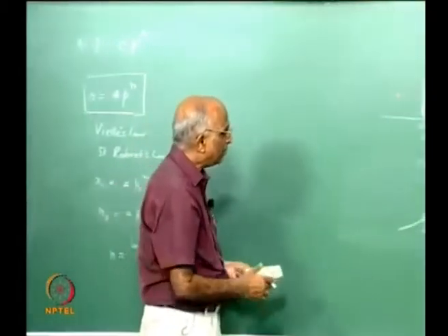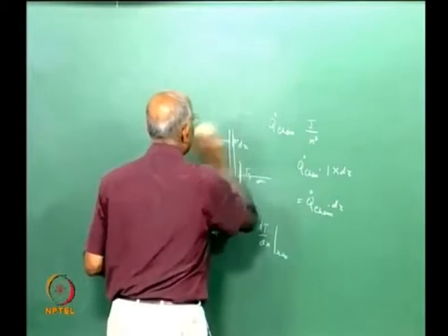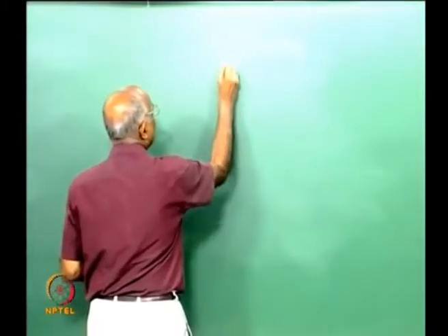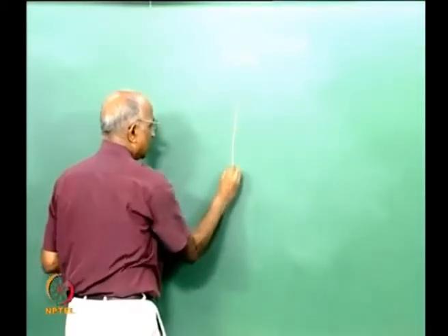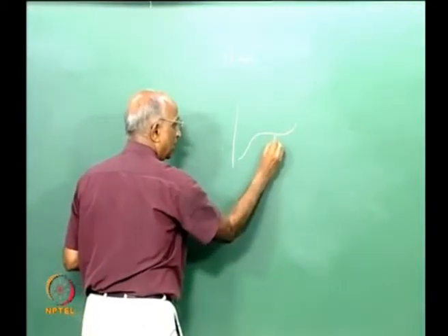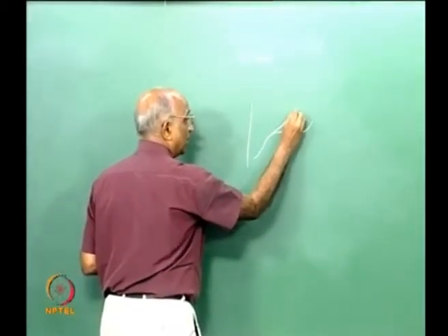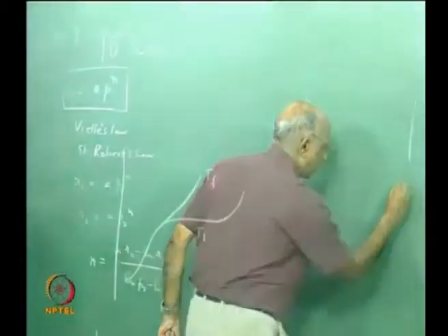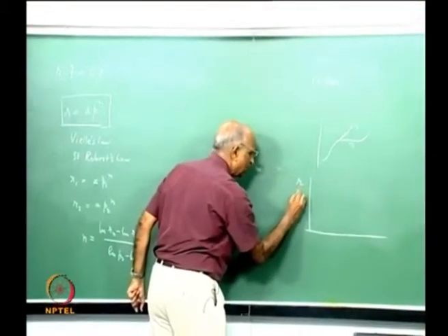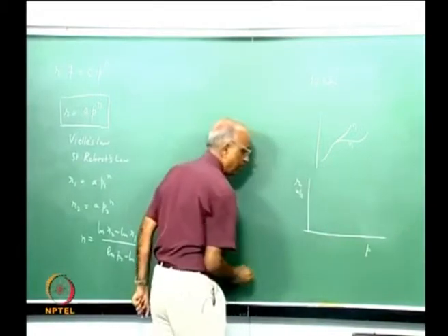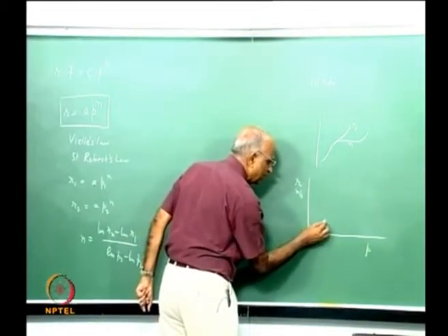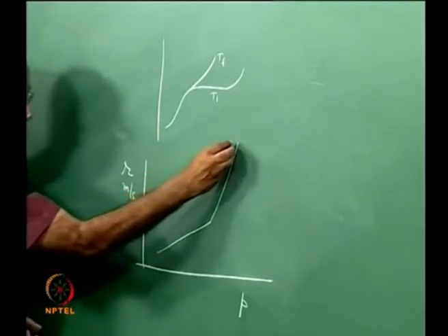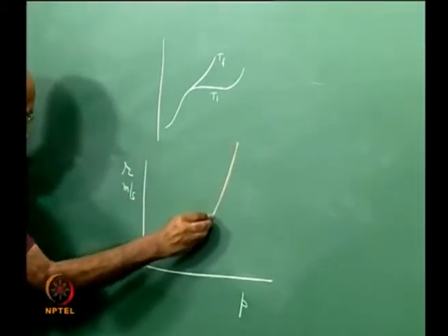But if the pressure is higher, in other words, if I have the ambient pressure in excess of, let us say, 10 MPa, then we told ourselves, well, there is no such thing as an intermediate T1 zone, it directly goes to something like Tf over here, more heat is conducted, and therefore if I were to plot the burn rate R, let us say in meters per second, as a function of pressure, at low pressures I have n which is something like this, when pressure goes up it goes like this, or rather the curve will not be very marked like this, maybe the curve will be something like this.